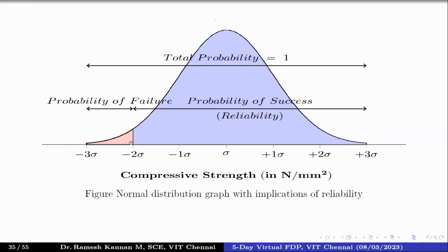If this probability of failure keeps on increasing, say for example, if it gets increased here, then that's a total disaster. Even though you have fruitful results and your compressive strength is pretty good, that's not going to be acceptable, because your experiment itself is not in the range of accepted limits. Generally it doesn't happen. Generally, it happens like minus 2 sigma can go to minus 1 sigma and so on. It will be something around 30%, 40% failures, but anything beyond 40% failure is totally not acceptable.